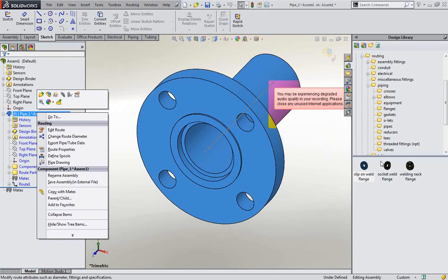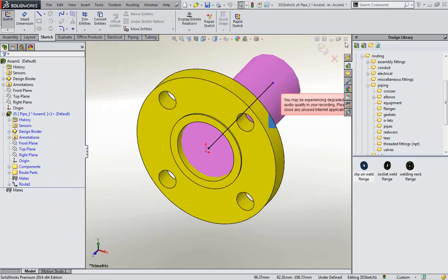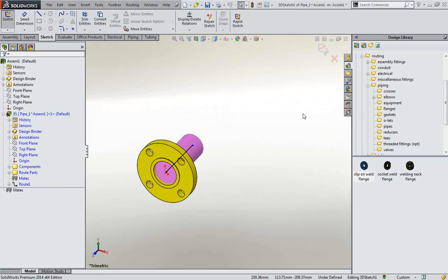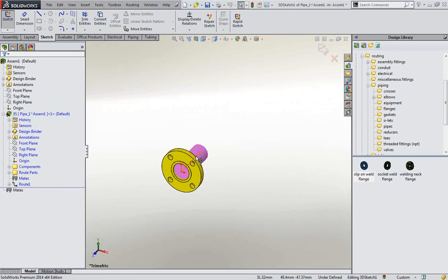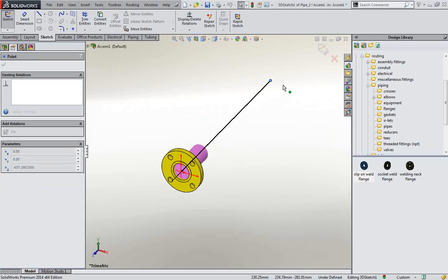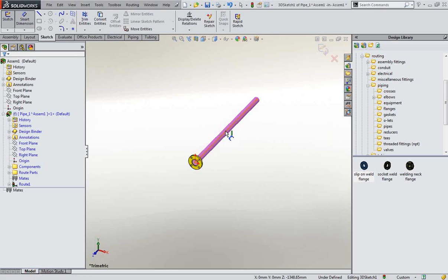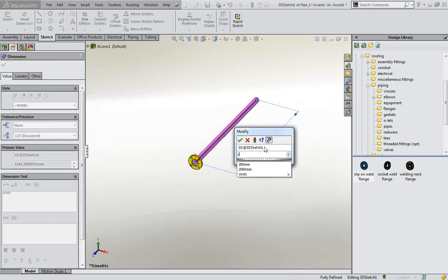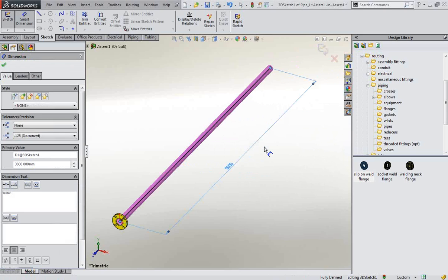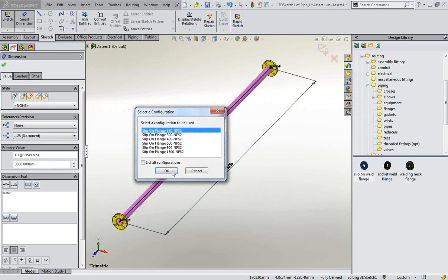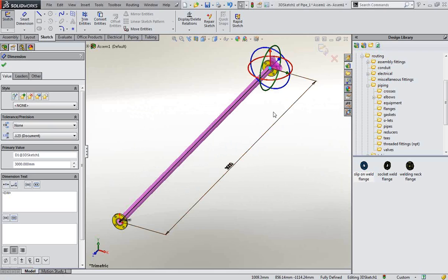Let me just bring this back. To generate a pipe's length, you can simply drag the line, or you can add dimensions to your line. In this case, I will just use 3 meters. So we finish this simple pipe with another end with a flange.